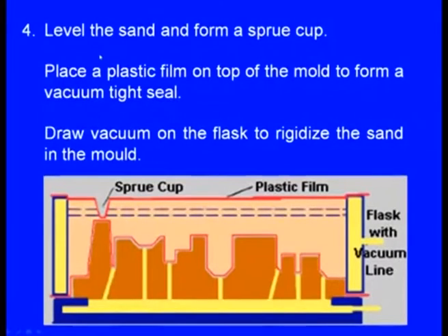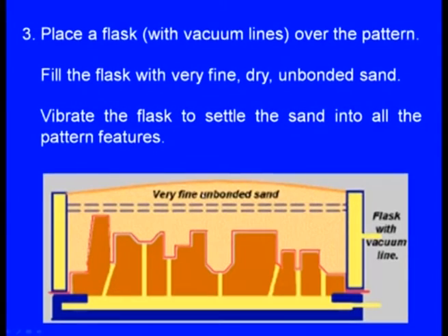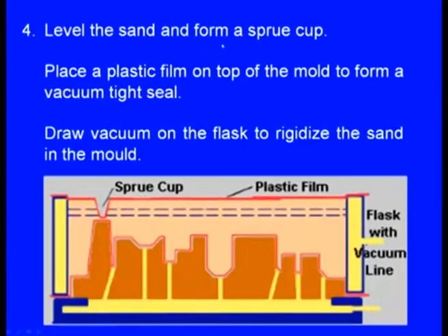Next step, there may be some excess sand. You can see here, there is excess sand. So, this excess sand must be removed. Level the sand and form a sprue cup. So, here a sprue cup is formed.